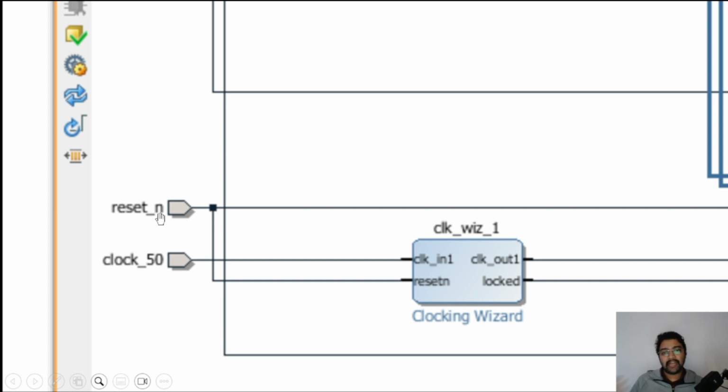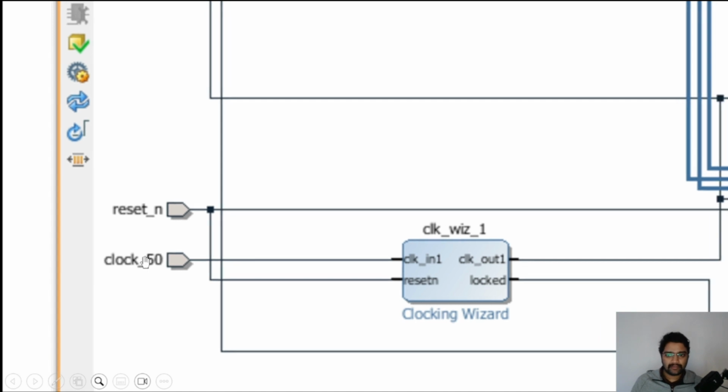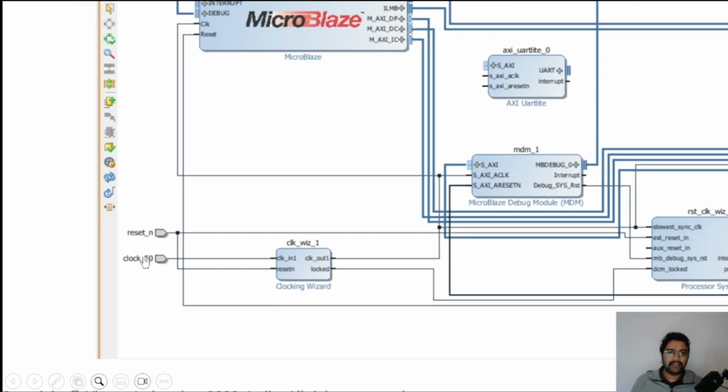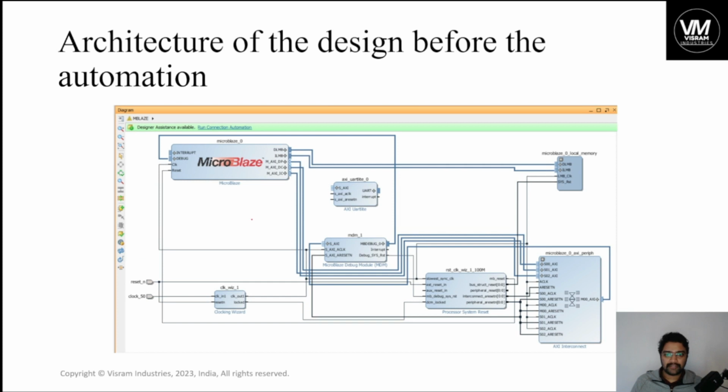You can mention it in your own style, but in the designs, it will be very good if you elaborate the names. Another tip while you are writing, and remember these names after you write in the VHDL codes and test bench codes as well, because you will be making constraints out of it. When you make constraints, you need to be very specific about the port names. So I'll show you in a later part of the class.